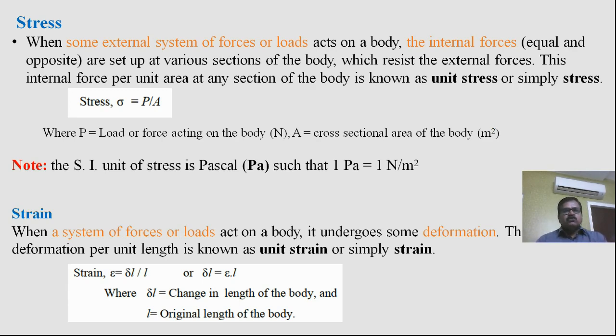So depending upon the types of forces experienced, the member is going to experience stress. So in today's session, let us discuss the simple stresses, the tension and compression. In simple terms, stress is the resistance offered by the body to the externally applied forces. It may be a single force, it may be a system of forces. Stress mathematically is the force applied divided by the cross-sectional area. The area is the resisting area and force is the applied force in the normal direction to the cross-sectional area.